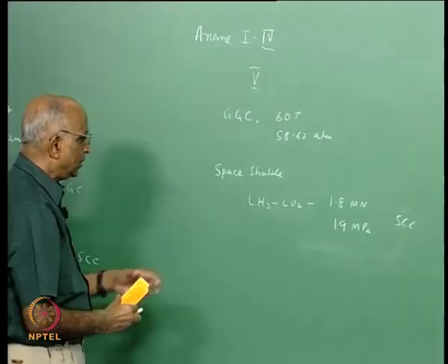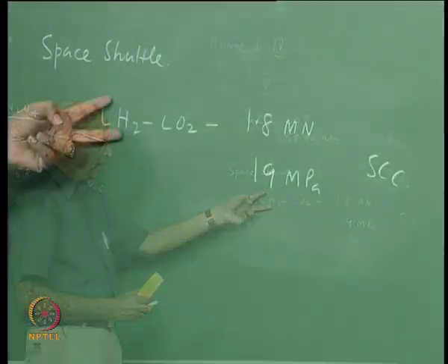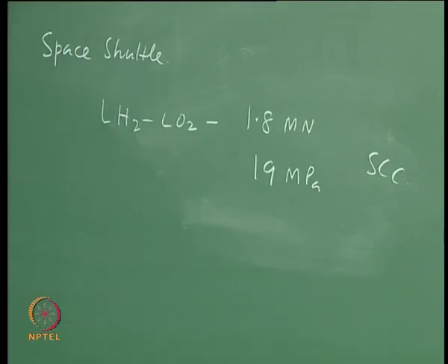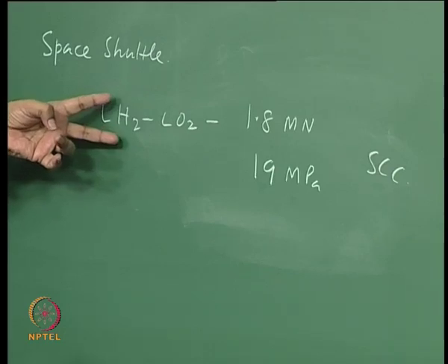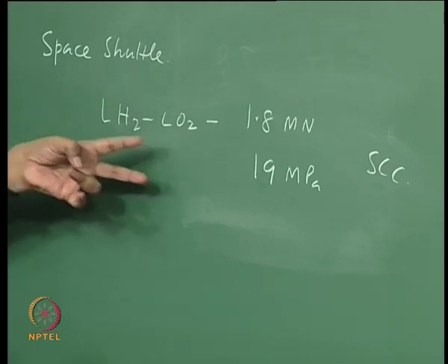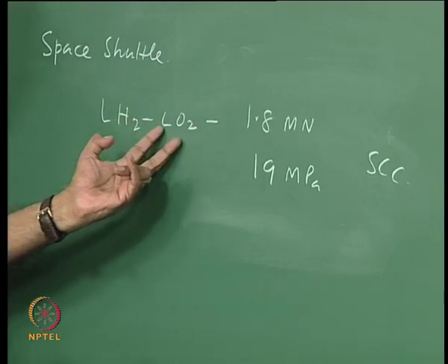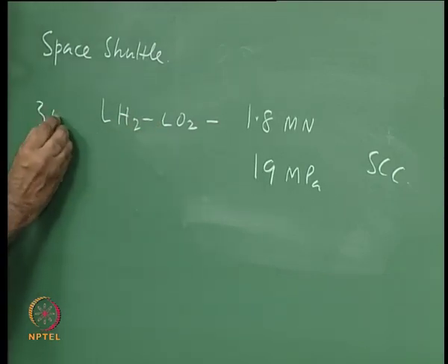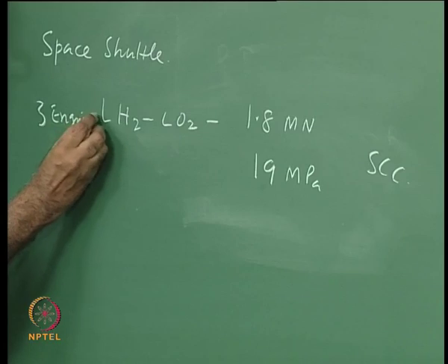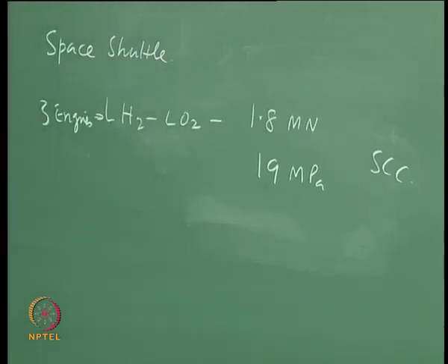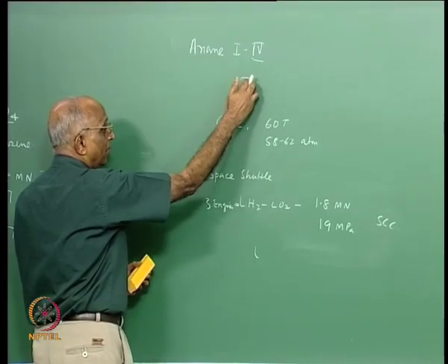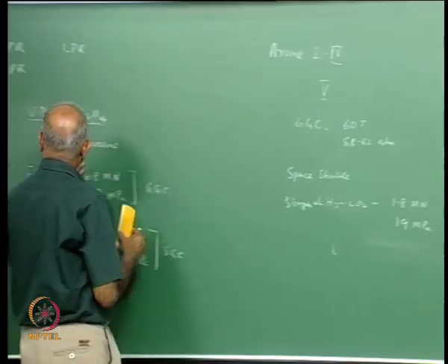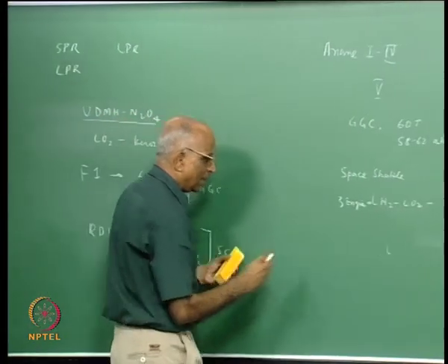See, even though the density of the propellant is small, they have a huge booster, and we have seen pictures of it on the back. You have a liquid hydrogen tank, they carry the liquid hydrogen, and you operate liquid hydrogen, liquid oxygen. You have 3 such engines which are used in the space shuttle. Whereas if you use the French type of things, again as I said, the Ariane 5 went off from using UDMH N2O4 to using LH2 LO2.